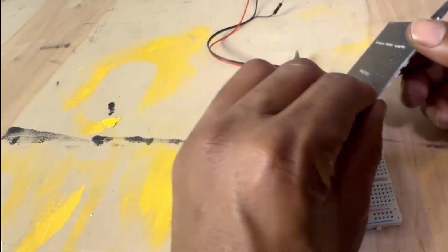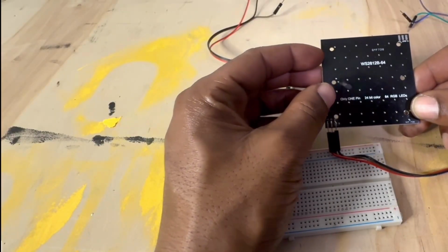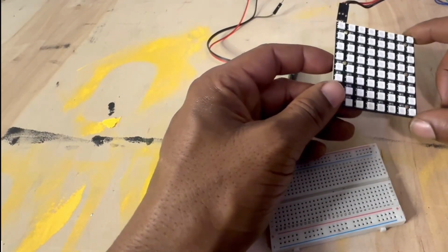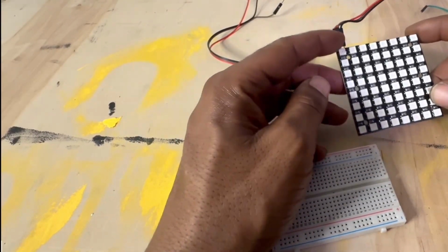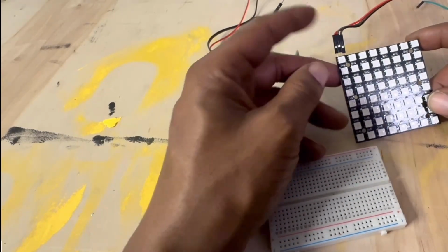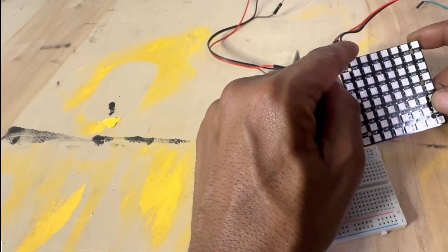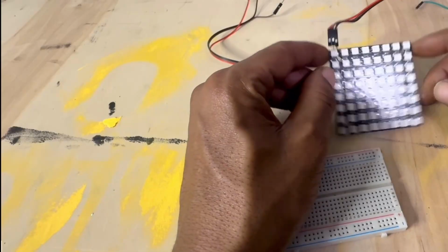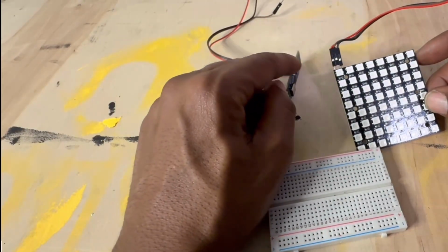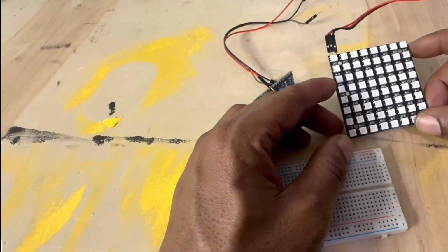This LED board that we're using is WS2812B. It has 64 lights in it. Just in case you wanted to test something out, but this can go on any board that has 3-wire output. I feel like those are the best wires to be using, to be honest. 3 wires, meaning one's positive, the other side's negative, and the middle wire is usually the data wire. So that gives you all the information coming from the Arduino Nano into the LED board.